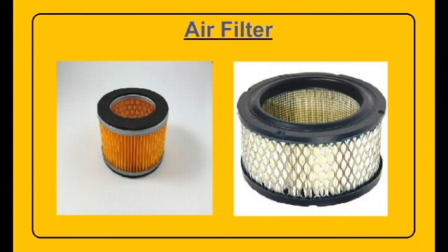Air filter materials: felt or paper, metal gauze or nylon strands. The purpose of the filter is to remove contaminants which would cause abrasive wear of piston rings. Deposits on valve casing can be a source of ignition. A very dirty filter will cause reduction in suction pressure, increase in compression ratio, and increase in discharge temperature, which may cause coke deposit, less airflow and danger of overheating coke deposits. In an extreme case, discharge temperature may exceed the auto-ignition temperature of lube oil, resulting in an explosion.